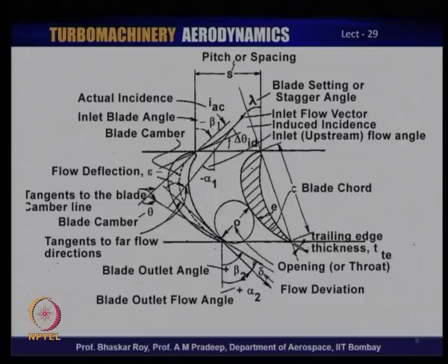This is a picture that tries to capture everything that the turbine has. You have to begin with the pitch decided upon, the throat area, which is typically done by actually drawing a circle over here, and then of course the inlet flow angle beta 1 and exit flow angle beta 2. As I mentioned, you can have a small flow deviation over here, which means the flow does not quite cater to either beta 2 or alpha 2, which would be in case of a stator.